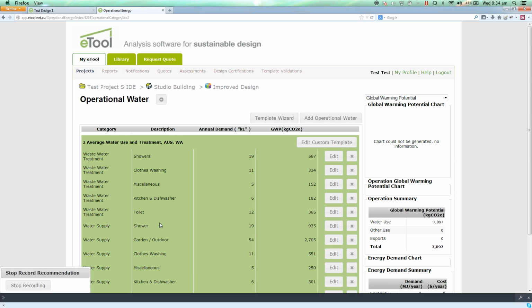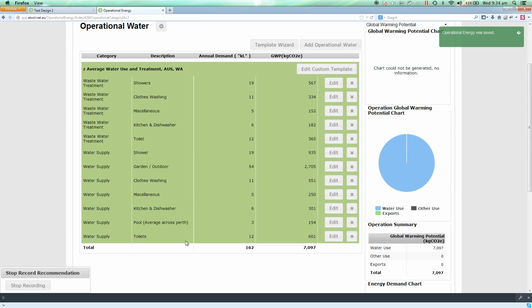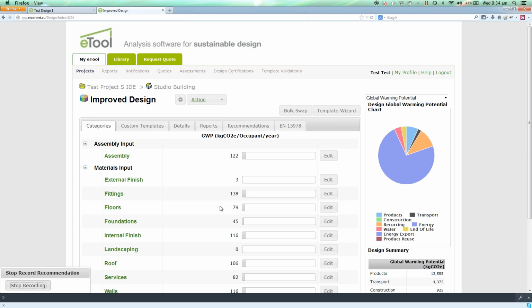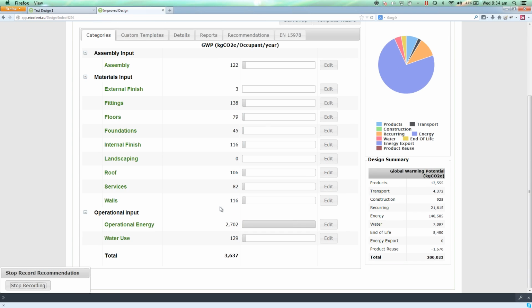So we've effectively just thought in our heads, okay, how can I reduce that hot water demand? Low flow shower heads is going to be a good option. We've got some assumed demand there, and I'm just going to reduce that demand for that water, the water treatment and the energy related to the hot water by the relationship between the old and the new shower head.